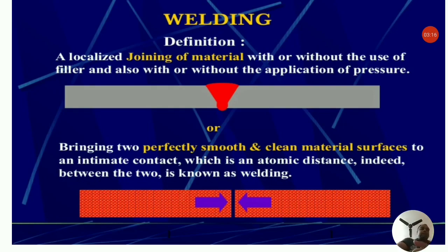And after that we use the fabrication process to join the materials, which is known as the secondary manufacturing process. Sometimes we can also consider the metal cutting processes, that is shaping or drilling or milling or any operations coming out of the lathe, as secondary. They actually come under the heading of secondary manufacturing process. So you can easily visualize that primary manufacturing process mainly deals with metal forming processes such as rolling, extrusion, forging, and the secondary manufacturing process mainly deals with metal cutting and fabrication processes.